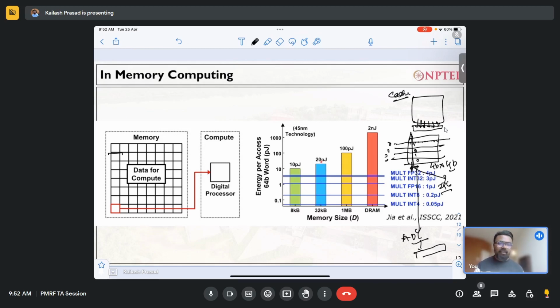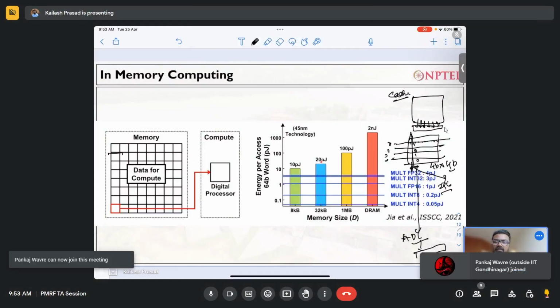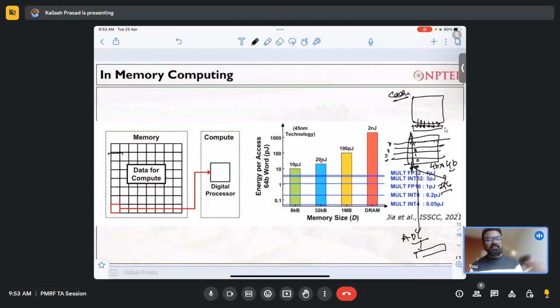The second thing is, if you are at, say, Ladakh, or the Sahara Desert, or Arunachal Pradesh, which is a very cold climate, or a humid climate like Mumbai, everywhere your chip should work, in all the range of temperatures. With the analog domain, there are challenges that, with temperature, things start varying. So now you have to take care of how you compensate for the temperature in the chip design itself. These are the circuit level things we are doing.